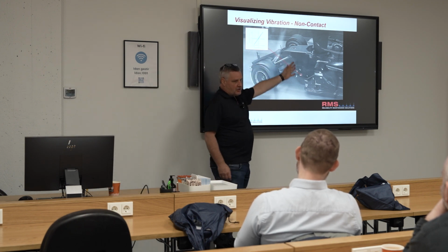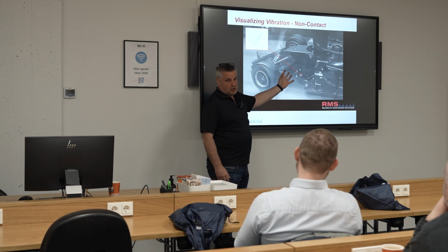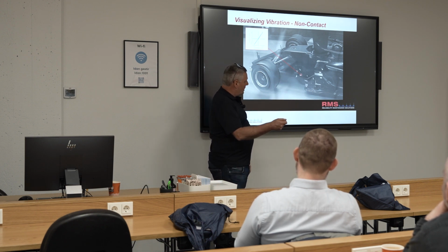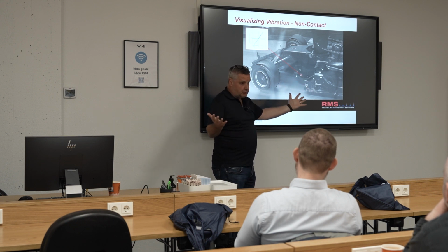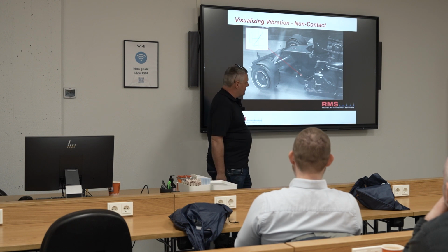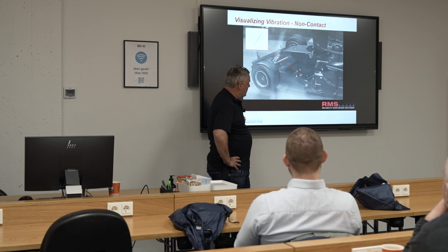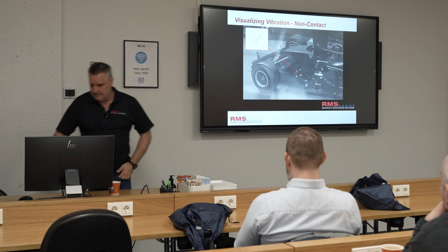Okay, but that's what I'm trying to explain there. We're saying that's non-contact measurement, just basically from a camera, from a video shot. We're used to using accelerometers, going around pieces of equipment, like we've done for years and years, and still do, because we still have to combine both technologies to get to the diagnostic capabilities that we want. But this is a great tool for doing things that are non-contact.